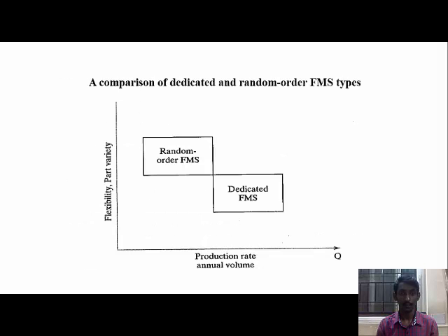This is a comparison of both the type of FMS based on level of flexibility. Random order FMS have more flexibility and part variety when compared to dedicated FMS, but production rate increases with the dedicated FMS rather than random order FMS.